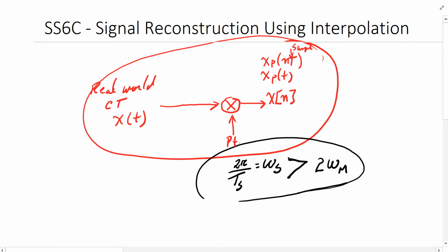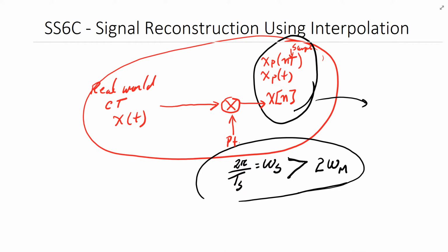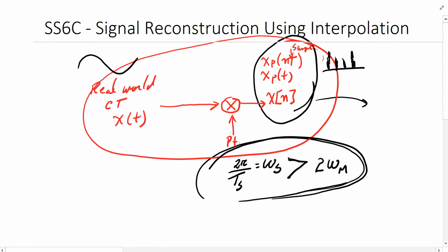We called this the Shannon-Nyquist sampling theorem, or simply the sampling theorem. The reason we did this is so we can use this in a computer or someplace and manipulate the numbers to do whatever we are trying to do, or store the data. Now, the next step is I want to recover. My real life curve looked like this. Here I have a bunch of numbers: first sample, second sample, third sample, fourth sample. I want to use these samples to recover the original signal. So we follow the sampling theorem, which means we have enough content to be able to recover it.